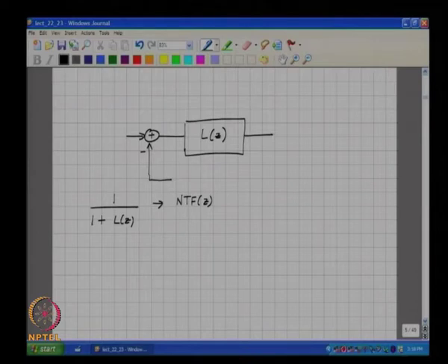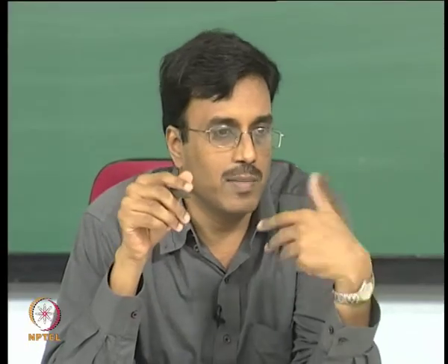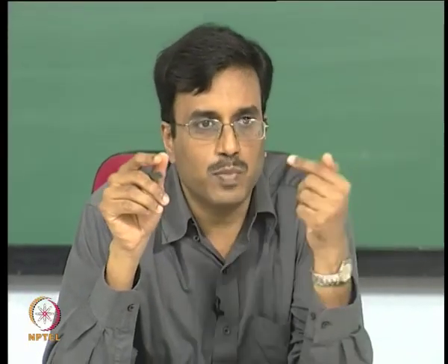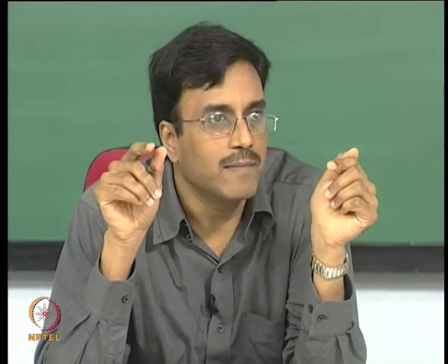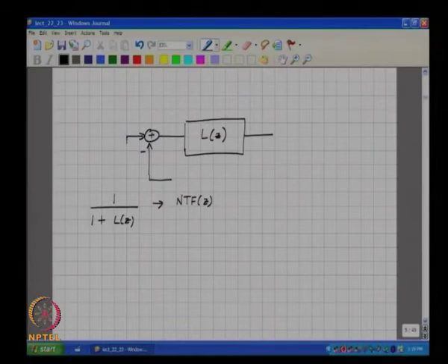Now, as we discussed in the last class, this system can be broken up into 2 as far as analysis of stability is concerned. If you do not like to think about it as 2 systems, given our background in analog, you can think of the input as being the quiescent value and replace everything in the loop by its incremental equivalent. Then the quiescent value becomes 0, so you can think of this as the incremental picture of the entire loop, given that the quantizer is non-linear.